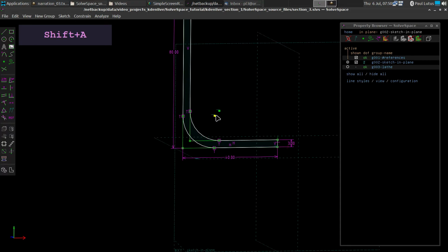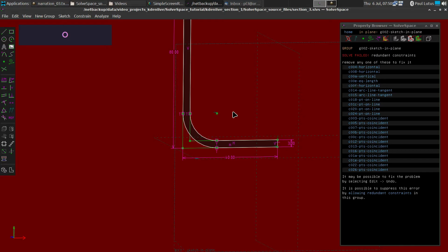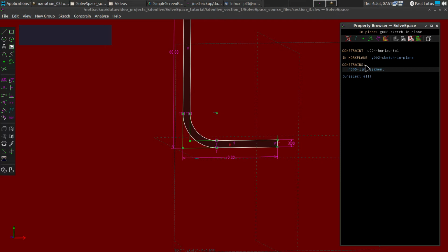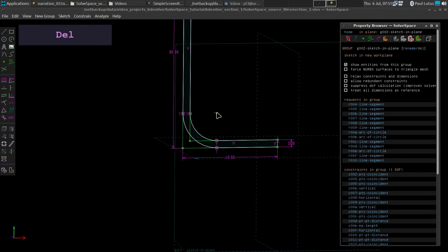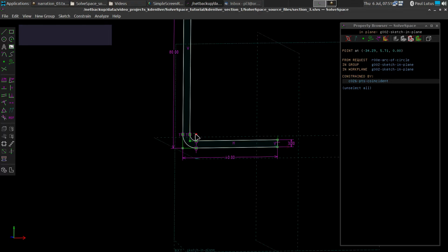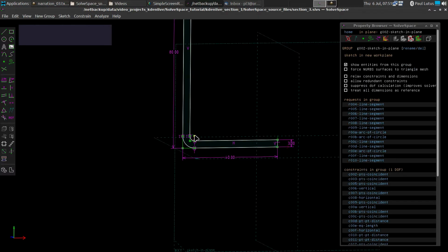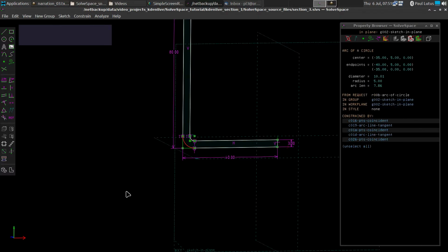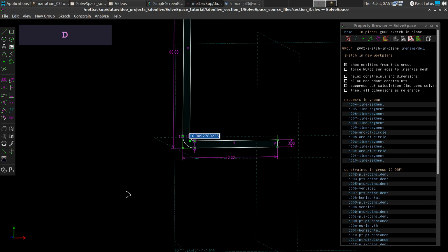Now, because I want this cup to have a certain appearance, I'm going to make these two, which are the center of the arcs, the same point in space. And we'll get rid of a redundant constraint. Now, if I go like this, with this point, I can choose the profile that I like just based on aesthetics. So that one looks pretty good. So let me click this arc here and press D for dimension.